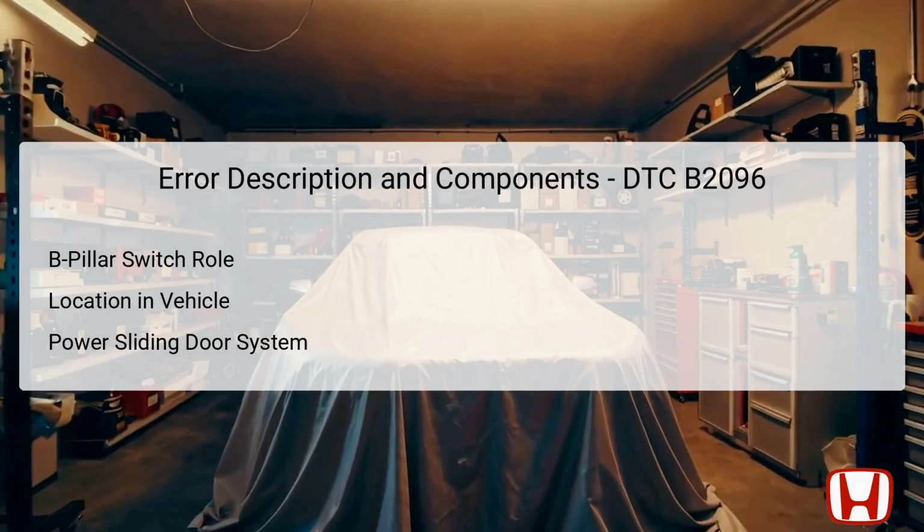The right B-pillar switch plays a vital role in the functionality of the power sliding door in the Honda Odyssey. It is designed to control the opening and closing of the right side sliding door. The switch is located within the vehicle's B-pillar, specifically positioned where the front and rear doors meet, on the right side. Being part of the B-CAN, Body Controller Area Network system, this switch communicates directly with the power sliding door control unit to manage door operations.